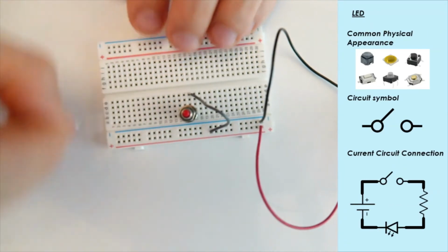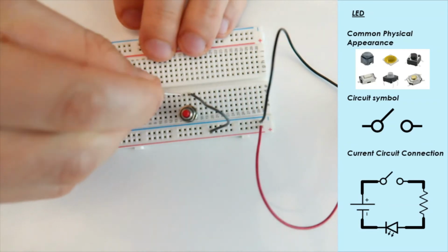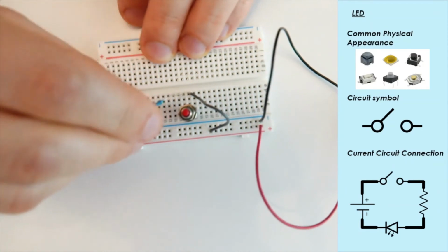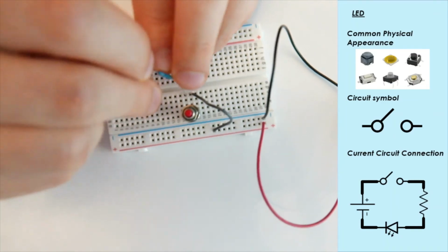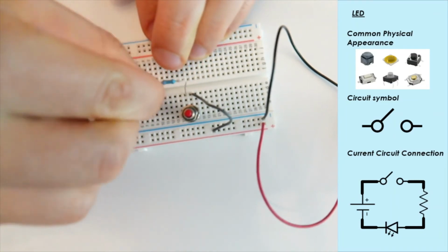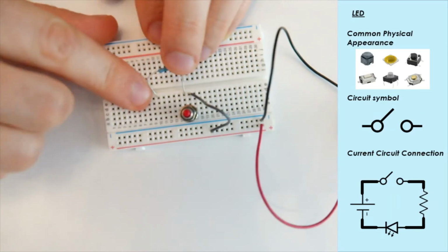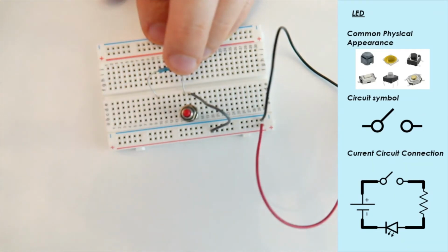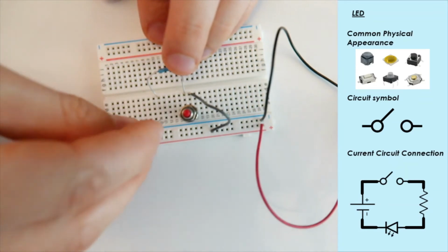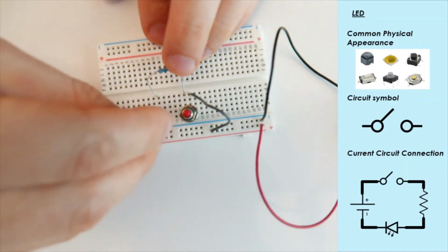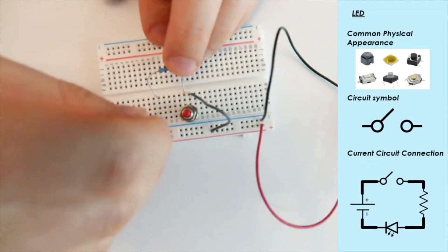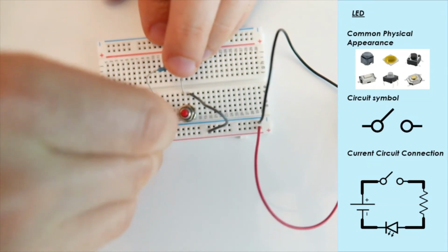We then take the other end of our switch, this rail here, which will only be joined together once we close down on the switch, and we're going to put that into this rail here. So this is now the other side where we're going to connect an LED, positive side into that same line with the resistor. Actually, let's make it this way around so it's easier to see.